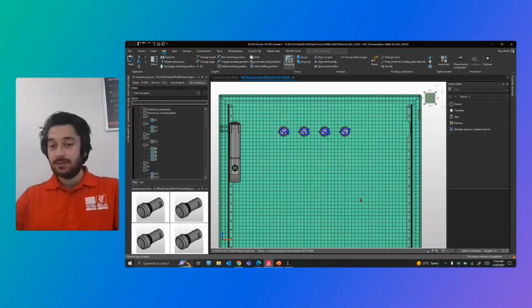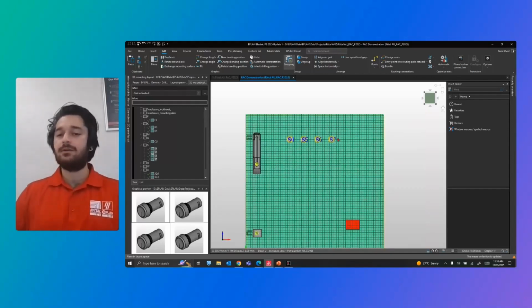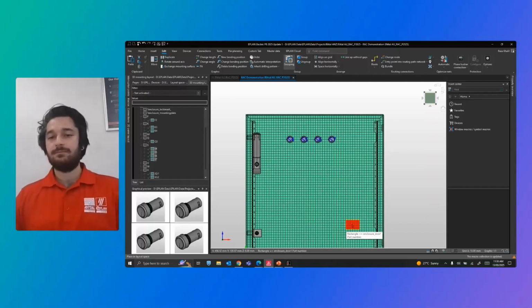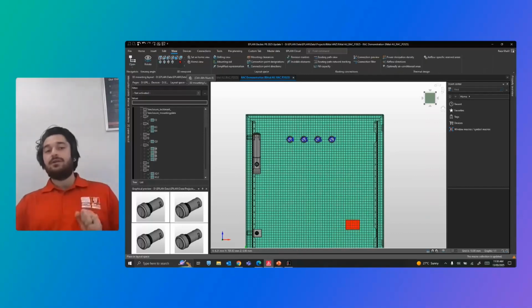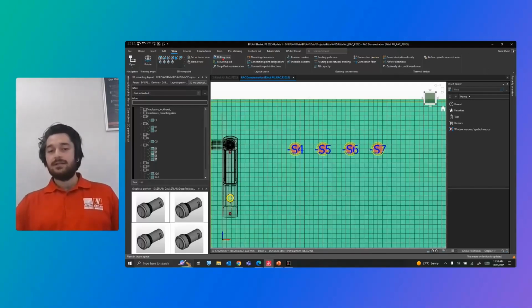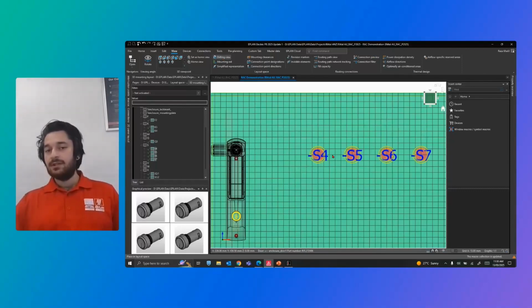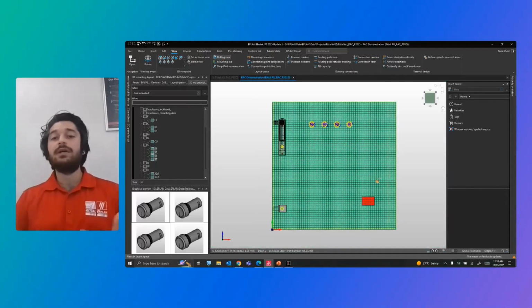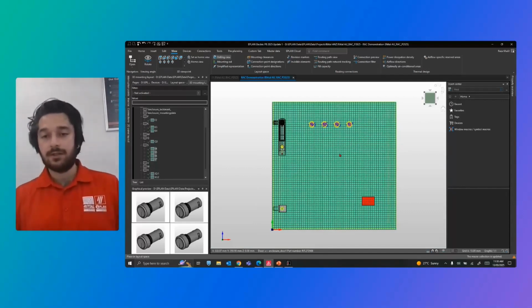Now, another interesting thing here that I want to show you, the moment you start placing these devices, of course, I have the cutout here manually that I placed using Rittal panel. What about devices? The moment you place a device that has a drilling pattern behind it, it actually gets registered. You see this red circle here? That is the cutout. You're seeing the cutouts for all of these individual devices. It's all getting registered automatically for you, which you can then push out directly to the machine.